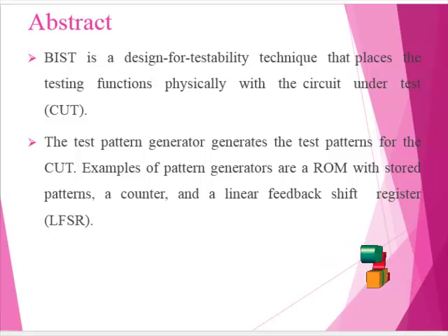The logic built-in self-test, originally developed for board, system, and in-field test, is now gaining acceptance for production test as it provides very robust DFT and is used increasingly often with test compression. This hybrid approach seems to be the next logical evolutionary step in DFT. It has potential for improved test quality. It may augment the ability to run at-speed, power-aware tests, and it can reduce the cost of manufacturing tests while preserving all LBIST and scan compression advantages.